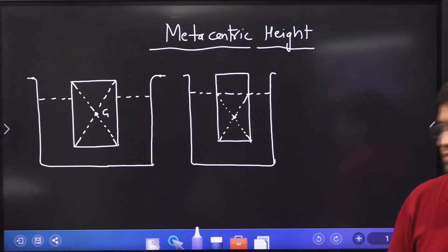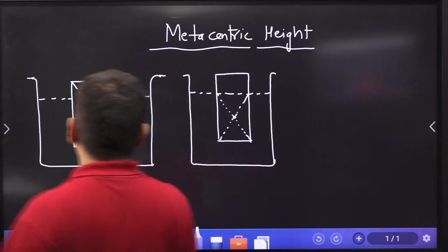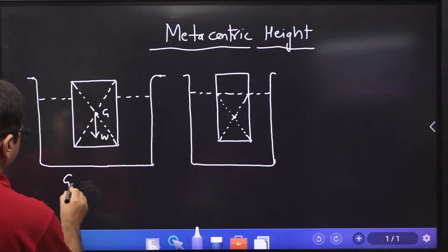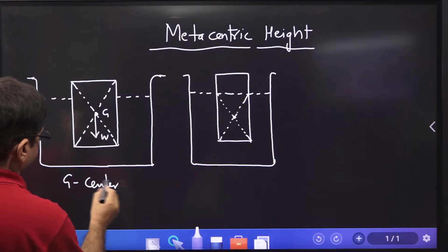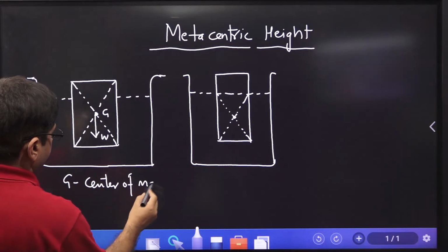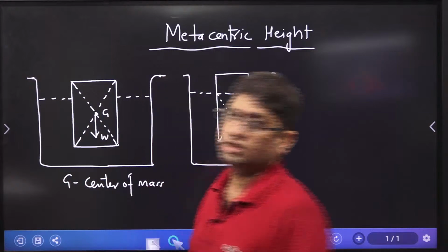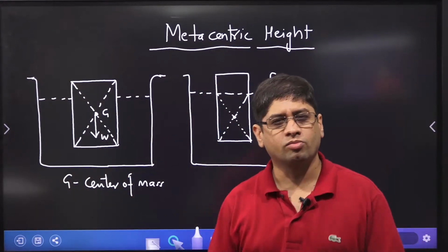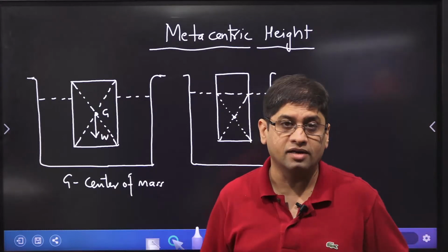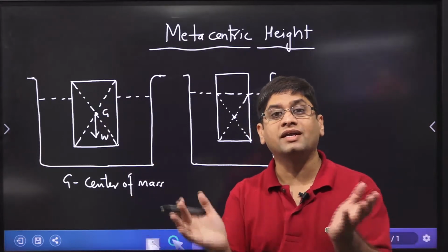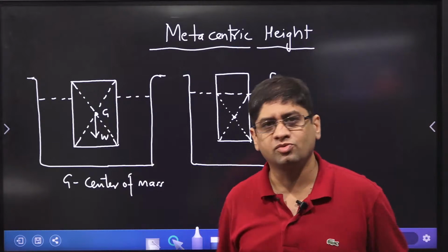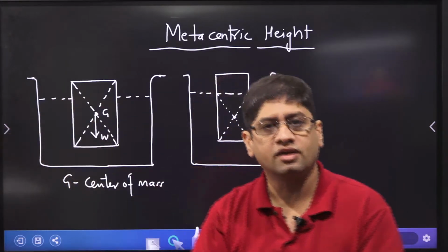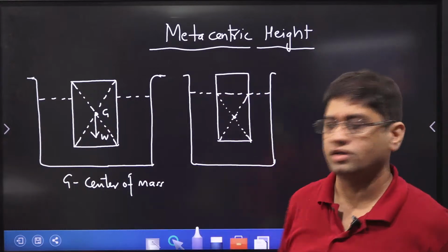See this carefully. Center of mass or center of gravity is a term. G is the center of mass of the body. Center of mass, if mass is uniformly distributed, is called the centroid. This does not depend on whether the body is in liquid or not. So how do you find it? It is a geometric center, if mass is uniformly distributed. Now the entire weight of the body is concentrated at this G point and acts vertically downward.